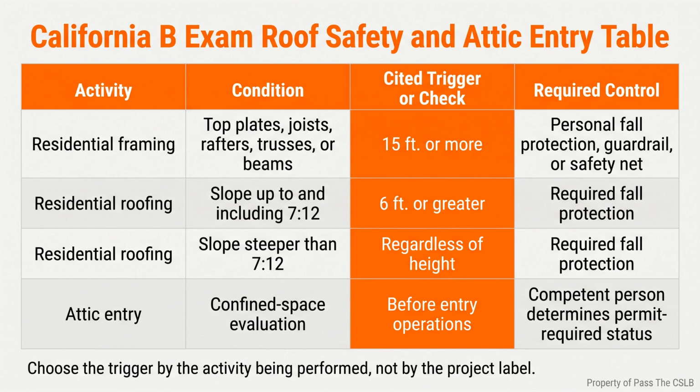The report gives curing spray foam fumes as an example of a possible atmospheric hazard. If a severe condition is present, the contractor needs the required written program, monitoring, and rescue provisions before entry. If it is not present, the evaluation still matters because the classification must come from the actual conditions, not habit.